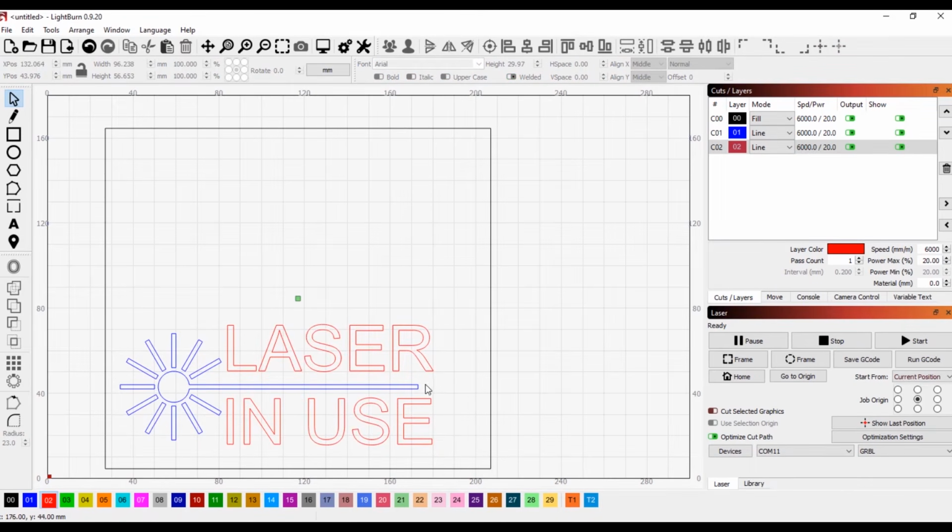So we need to extend this out to come to the similar position as to where the R and the E end. Now, if we select the item and we just use the anchor points to adjust this, what will happen is if you see where the circle was, that becomes an ellipse shape because we're adjusting the whole shape together. What we want to do is just move these 2 points on the end. So we'll undo that, Control Z, or you can use your buttons up here.